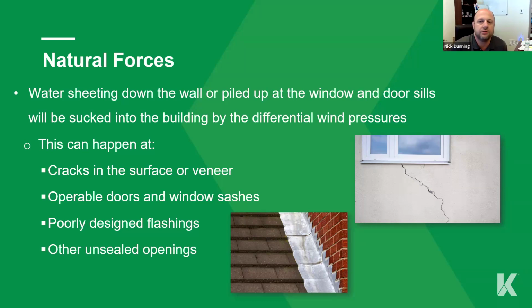They don't lock their windows, especially impact systems, because you have to have a certain resistance against the water intrusion, so the seals and other things are very tight on them, which means if you're not locked, that sash will be open a little bit. So we've actually had new buildings that have new windows and doors that pass water testing, all that fun stuff, and they get water intrusion during storms because people didn't do something as simple as locking the doors or windows.